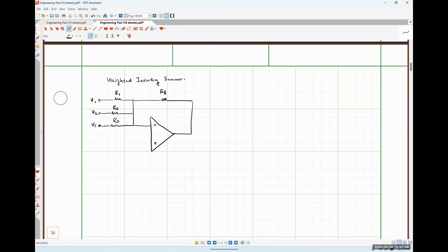So if I connect these input signals on the inverting input side, I can actually have essentially an infinite number of inputs and everything will work out pretty okay. We can do a non-inverting summer amplifier, but the math gets real gross real quick because each individual input scaling factor is just going to kind of go bananas, not particularly well behaved. So usually addition is performed using the inverting style of summer like this one.